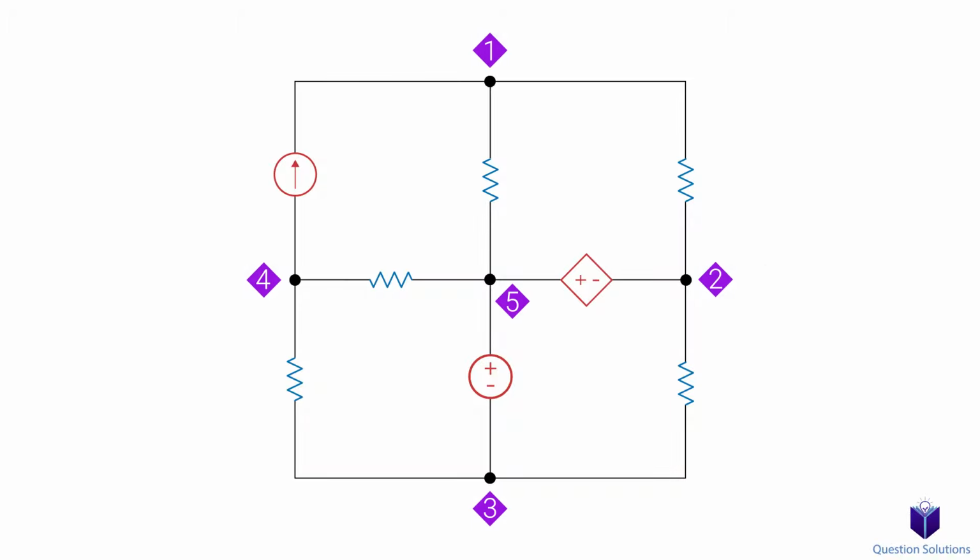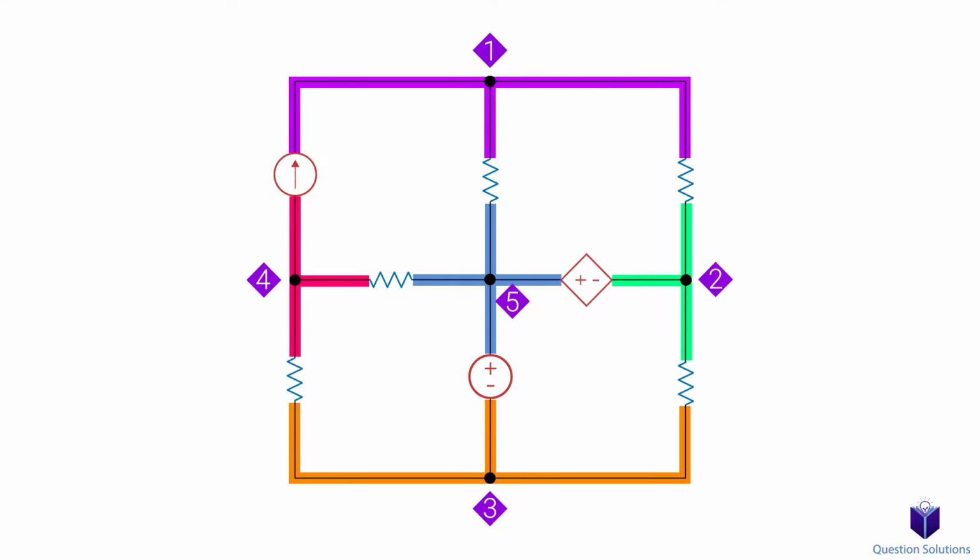It's a point of connection of 2 or more circuit elements. Assume we start from this point and keep moving until we reach this resistor here. The path we covered is a single node. Here's another node. Notice how the entire bottom of this circuit is a single node. In simple terms, a node is one end of a circuit element that has conductors attached to it.